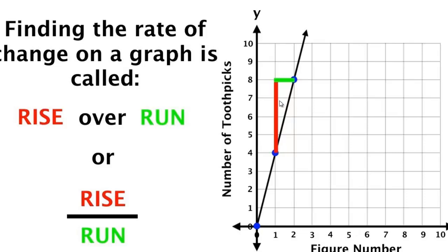Now for this to happen, we need an input coil that's only going to probably have maybe 1 turn. We need to make sure that our input coil is very, very low impedance, very low DC resistance, so that we can push 4 amperes through it as quickly as we possibly can, so that our partnered output coils see a very fast change.